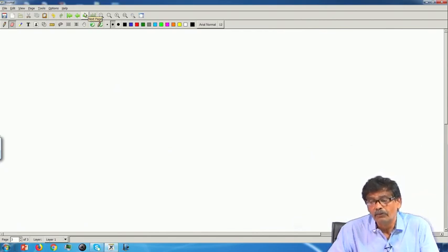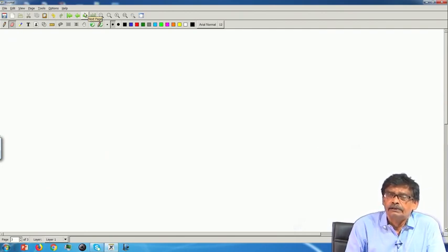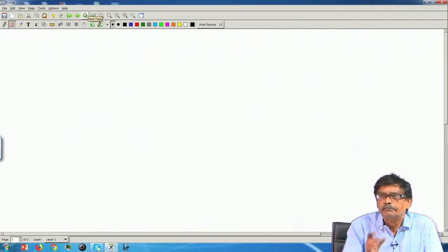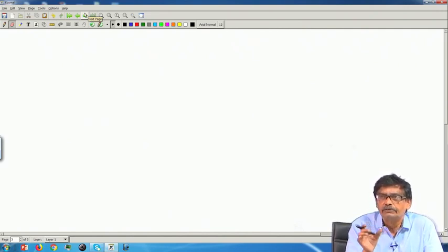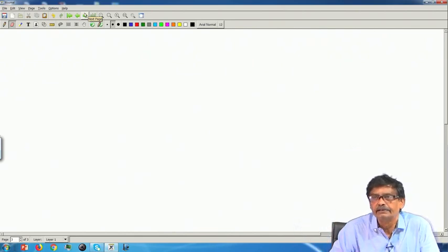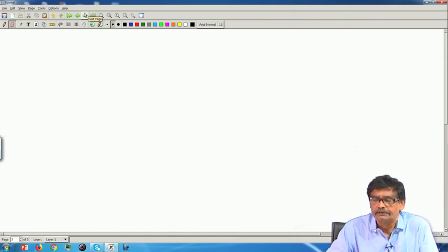So, now I know that so far as connections are concerned, the only thing you will ask is where are my primary terminals with polarity marking, A1 A2 capital, where is secondary small a1 a2 and so on. Then you can connect it, and it is the same for both the kinds.